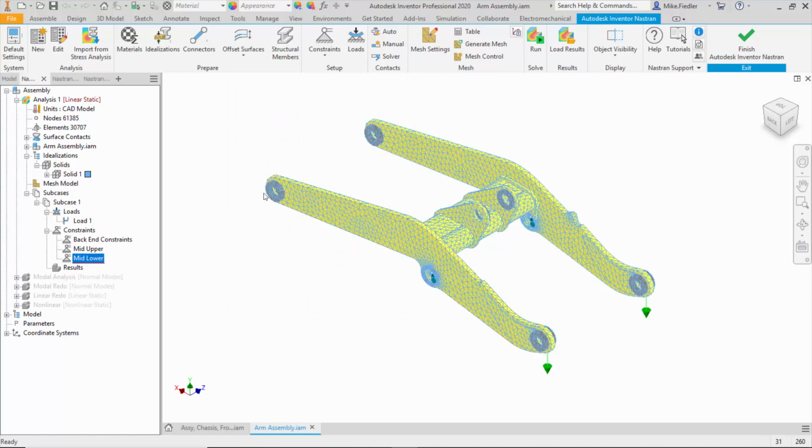If you imagine passing a cylinder through those regions that we have constrained, we cannot use the same pin type of constraint for all three of those sets. So I had to break them up into, again, three different applied constraints where the ones that I have chosen all would have the same cylindrical axis. But no big deal. It doesn't take a whole lot of time to set up.